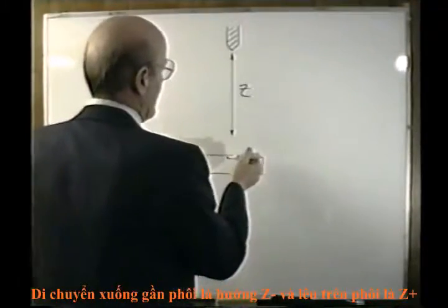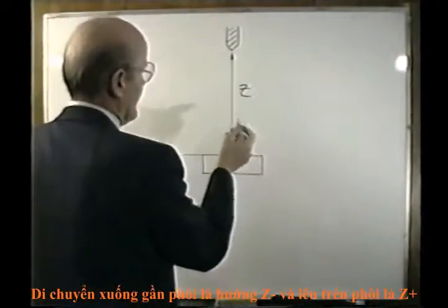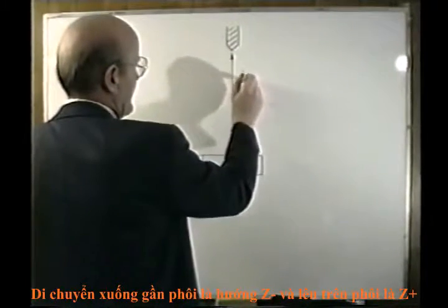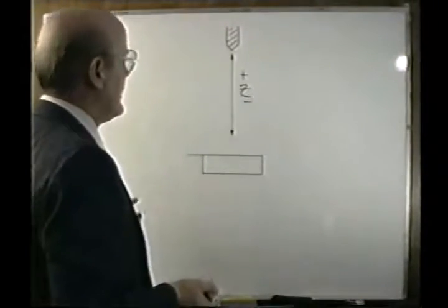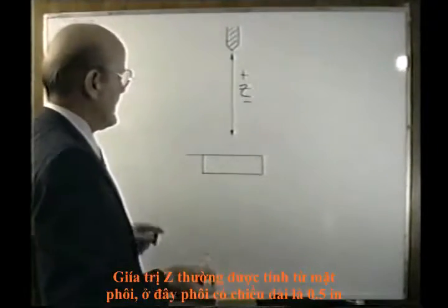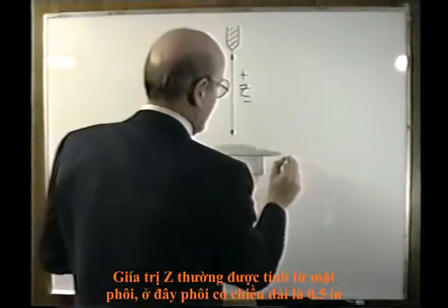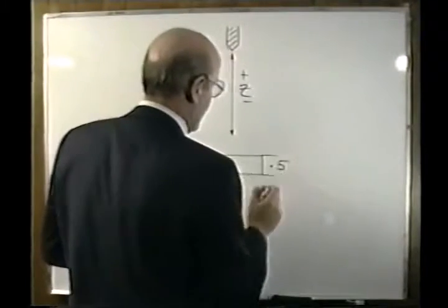And the further we go away from a workpiece, let's assume this is a drill and this is a workpiece, the bigger the numbers. And the closer we get, the smaller the numbers. Now, the way we set this up is that the top surface of this work part, let's assume this piece is maybe 1/2 inch thick, like that.